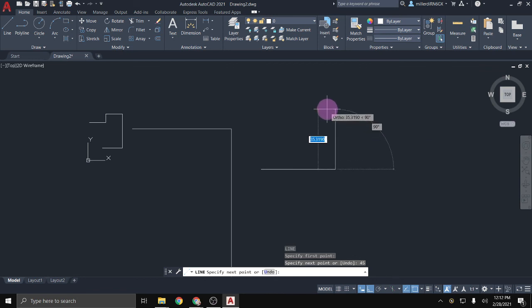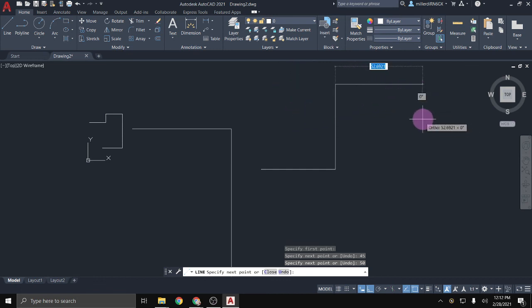direction. So a lot of students using the laptops tend to like ortho mode a bit more, just because with polar tracking, you do have to make sure that your cursor stays put while you then type your distance in. With ortho mode, if my cursor slips a little bit, then it's not that big of a deal, because I'll still have that horizontal line.